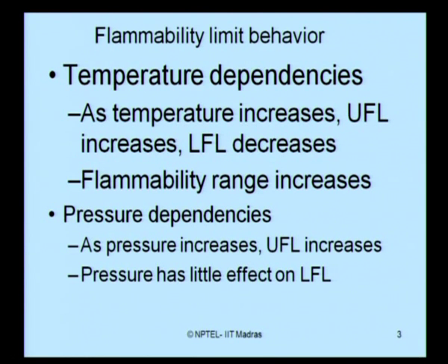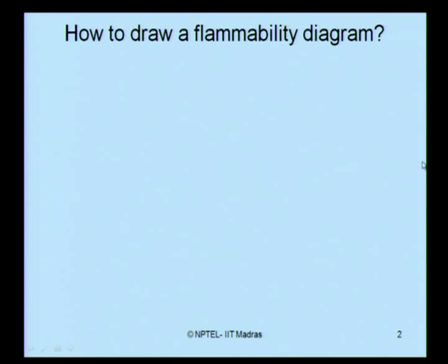On the other hand, look at the pressure dependency. We have already shown that the upper flammability level increases as pressure increases, but the pressure has less influence on the lower flammability limits. Now ladies and gentlemen, let us see how to actually draw a flammability diagram. The following steps are very important.